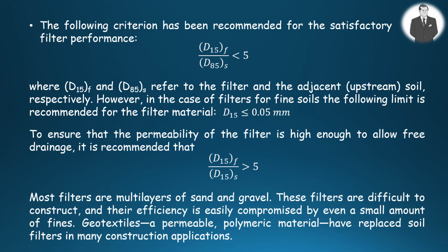Most filters are multi-layers of sand and gravel. These filters are difficult to construct, and their efficiency is easily endangered by even a small amount of fines. Geotextiles, a permeable polymeric material, have replaced soil filters in many construction applications.